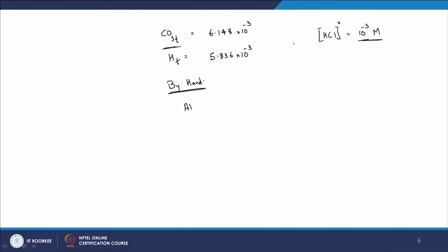So you know the alkalinity from the previous session, and by subtracting this particular acid concentration from the alkalinity, you can calculate the new alkalinity. What am I trying to say here? Let us try to plug this in. So, alkalinity after addition of HCl is going to be equal to alkalinity initially from part B, minus the concentration of strong acid added. And why is that again? Just think of this now.